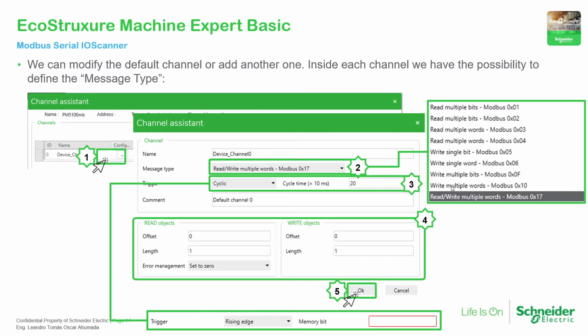Okay, it would depend on the variable that you want to read. Then you need to specify the trigger. The trigger can be cycle, so every time that you have configured, the PLC is going to read and write information, or you can configure a variable to trigger the channel to start the communication, read and write.